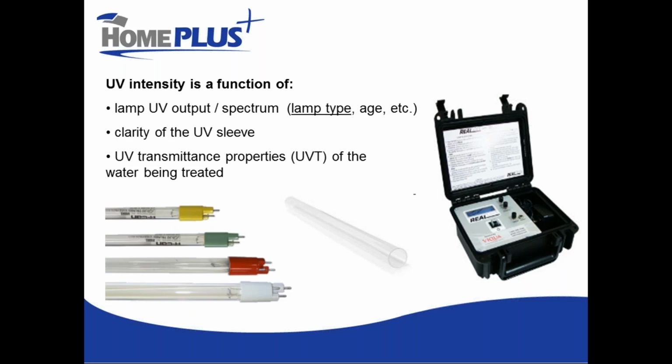So important to note on the latter part, some of those organics can cause a tint or color change in the water. You know, tannins typically have a tea-like color that can be anything from very faint to very, very strong. And that's kind of an obvious potential impact on our UV transmittance.